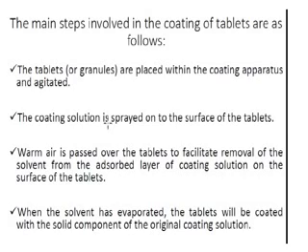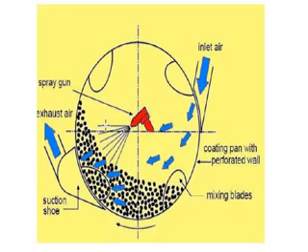Then we spray that solution on your tablets with the help of various instruments like guns and pans. After that we provide a dryer to dry the tablets and evaporate the solvent, and then we can prepare your final coated tablets.